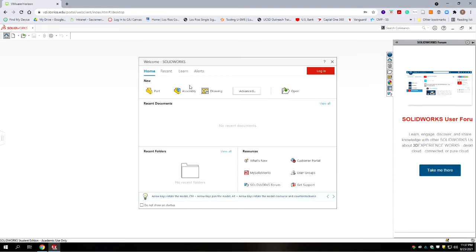The file itself doesn't have any geometry in it, but it's like a library of parts and associations between those parts. And then the drawing file can be driven from either one of them to make drawings at the part or assembly level. Once you create associations between these files, you have to keep them together. So again, this is a .SLDPRT, this is a .SLDASM, and this is a .SLDDRW file.